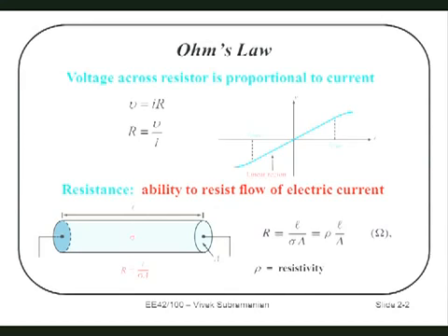Do you know why they use superconductors there? The underlying reason is actually the same as the large coils. Because you've got these tracks that have to run long distances, it allows you to have a loop of current flowing without significant loss. There's current flowing through this track. The track's really long. If it had resistance, you'd have losses, and then that causes issues. That's the underlying reason.